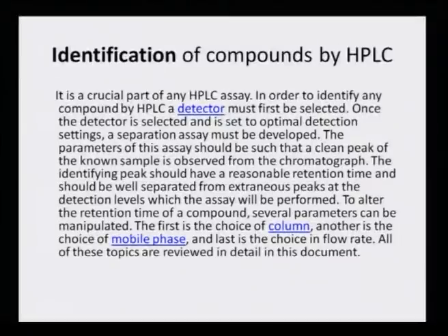Identification by HPLC, or with the help of HPLC, is a crucial part of any HPLC assay. In order to identify a compound by HPLC, a detector must first be selected. Once the detector is selected and set to optimal detection settings, a separation assay may be developed.